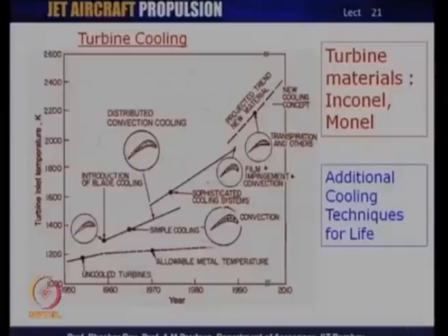Now, the additional cooling technologies that I was talking about, that is the additional film and impingement cooling, essentially render more life to the turbine blades. The life we are now talking about, according to present regulations of turbine usage, has to be of the order of something like 10,000 working hours or running hours.